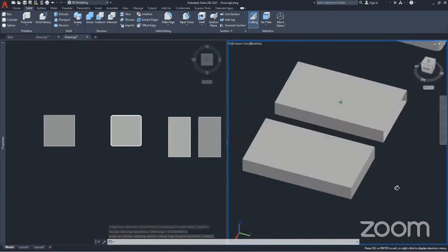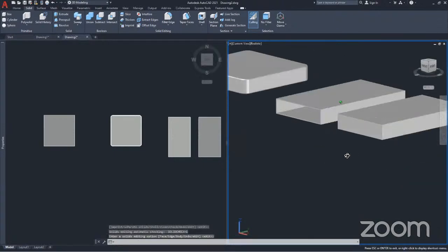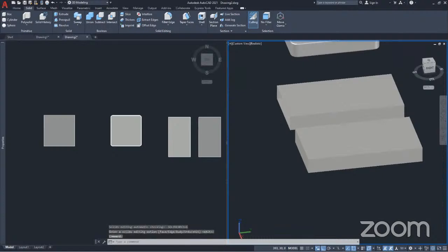I want to create the inside base. So now creating the inside base, I'm going to use this part. But before I do the creation of the inside base, I need to reduce all sides by 0.5, so when I create it, it can fit in. So I'm just going to be using my press pull tool. I'll select here and go inside by 0.5.